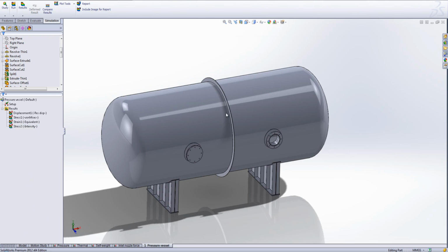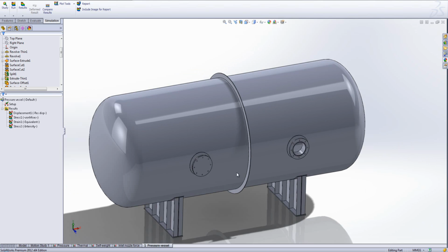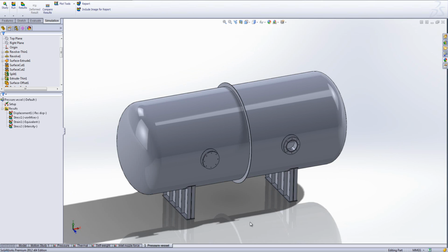And now our nozzle flanges and the cover have been analysed, like we said, using solid elements due to their thickness against span ratios, and also because we have included the bolt connections on the lid side. Now the ASME codes don't specify the limiting stress intensity values for these components. Instead, for flanges, it states limiting values of longitudinal, radial and tangential stresses.